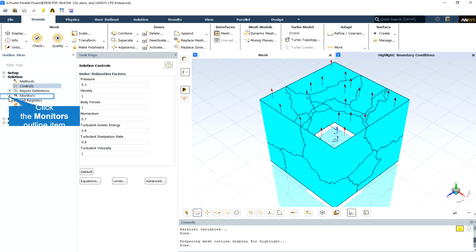Occasionally, you may make changes in the under relaxation factors and resume your calculation, only to find that the residuals begin to increase. This often results from increasing the under relaxation factors too much. A cautious approach is to save a data file before making any change to the under relaxation factors and to give the solution algorithm a few iterations to adjust to the new parameters.